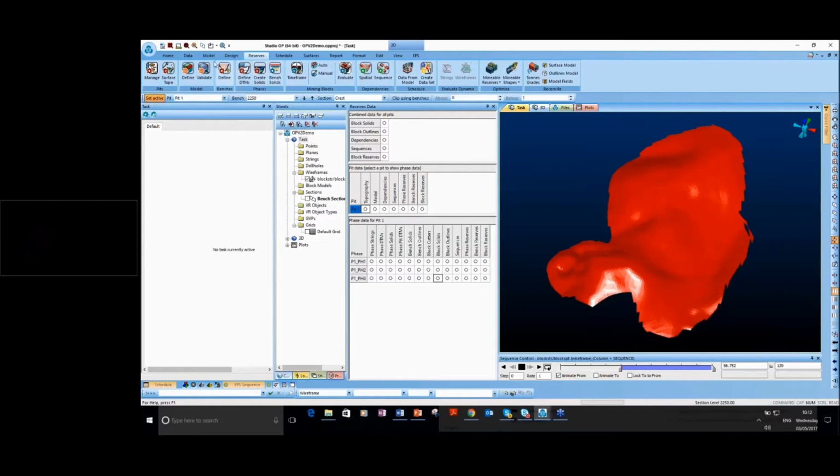In the Task window, as I said, we follow a workflow from left to right. First of all, we introduce the pit number and any topography. We input any block model. This block model is used for calculation of the reserve for each mining unit or mining block. We define the benches, and I explained why we introduce these benches.